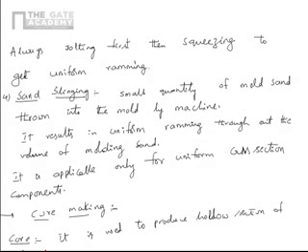If you prepared a cylindrical wooden pattern, kept it in the mold and filled in the molding sand, the molding sand will go inside the cylinder also. You can't remove it without breaking the mold, and if you break the mold, you can't prepare the casting. So to avoid that, the core is used.